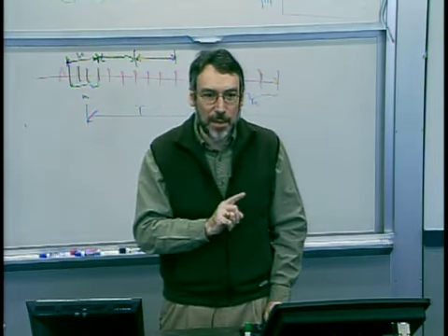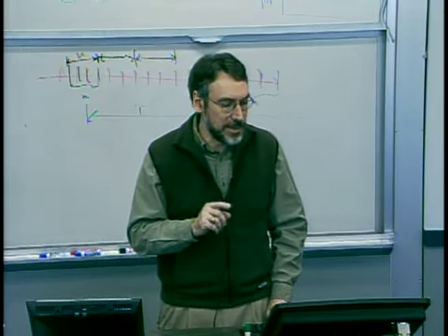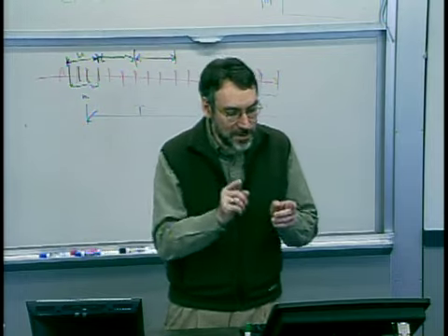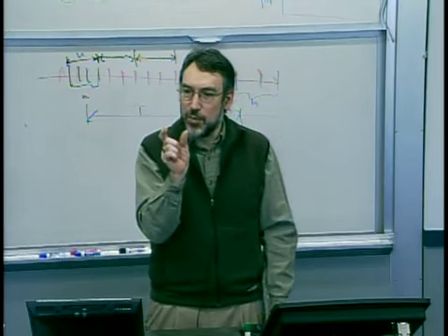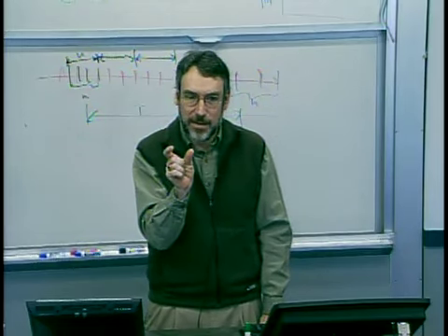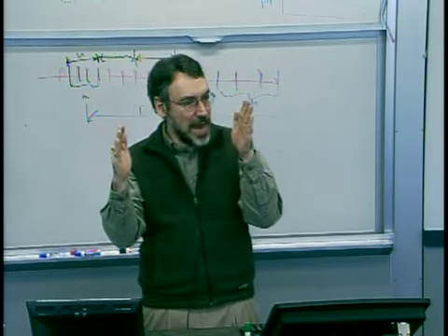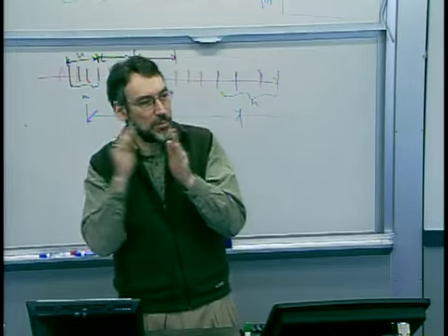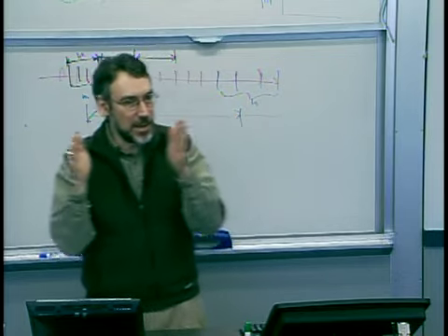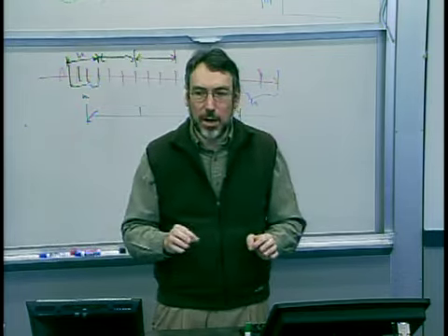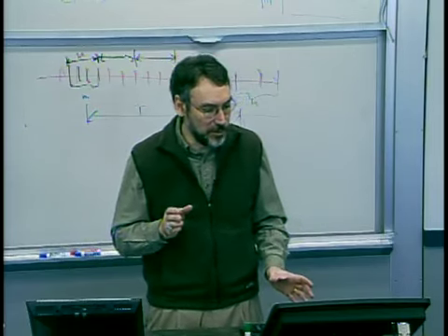If you also want to worry about mean, and you often do, another measure is the CPK. And what that looks at is the shortest distance, either on the right or the left of the chart, between your spec limit and your mean. How many sigmas apart is your mean from one of the spec limits? And divide that by 3 sigma on either side. Right? And so now you're penalized for being offset from your target. Okay, so let's look at this graphically and get a little bit of a feel here.